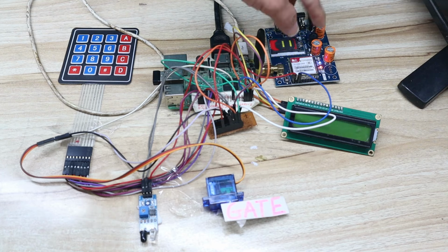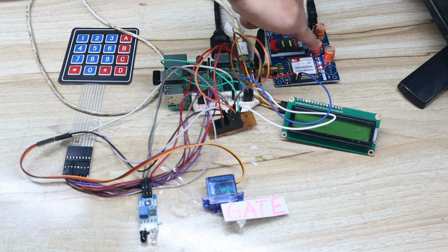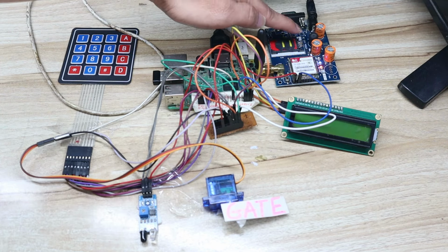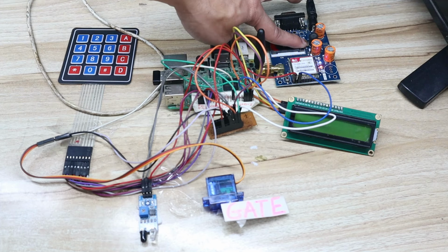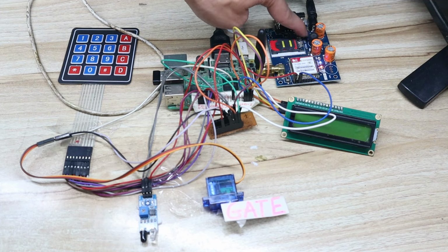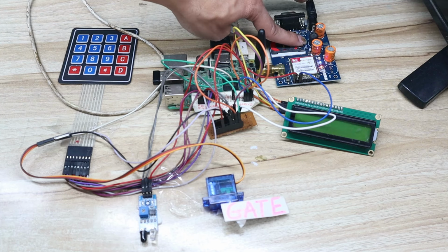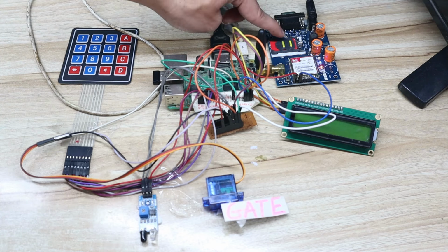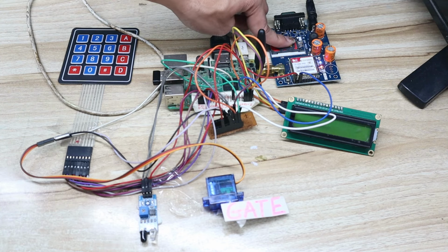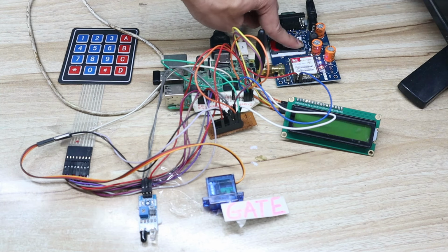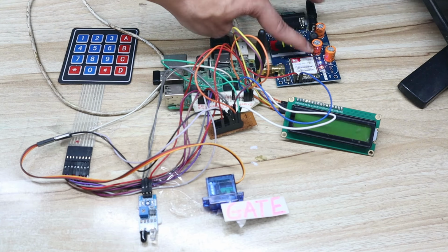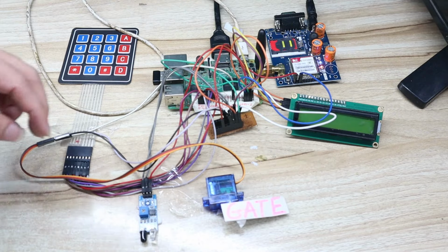If it is blinking quickly, that means there is no range. If it starts blinking every 2 to 3 seconds, that means there is a range on this GSM modem. Then check whether at this place your GSM modem gets heated or not. If there is heating, that means your GSM modem is faulty. Then you can give a call to this GSM modem. If you find the ring on your mobile, that means this GSM modem has the network. All these preconditions you should verify first before giving power supply to the Raspberry Pi.